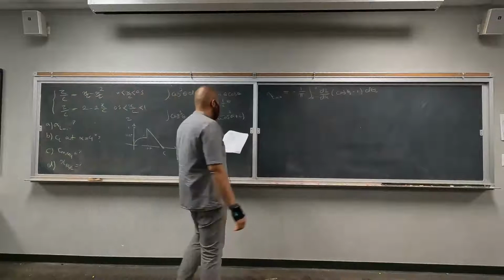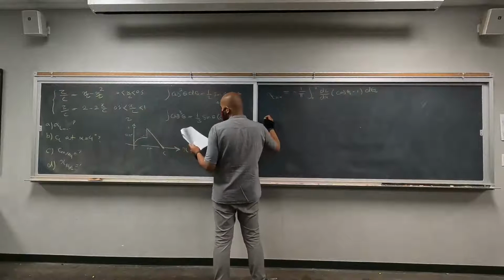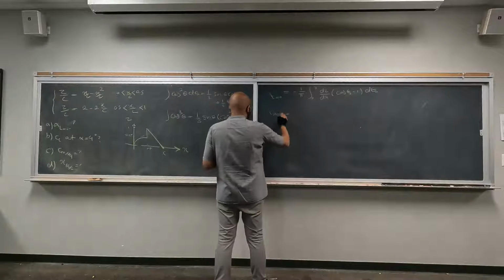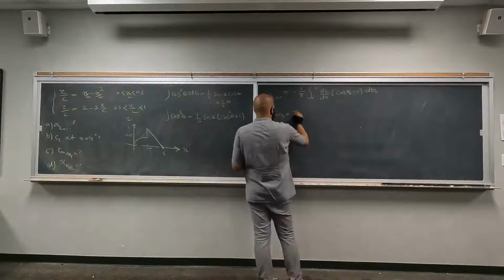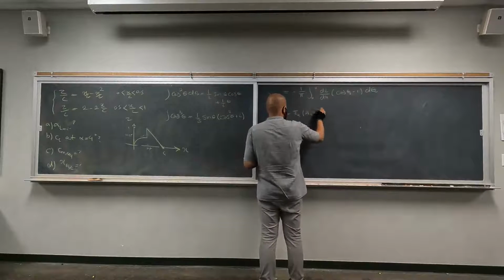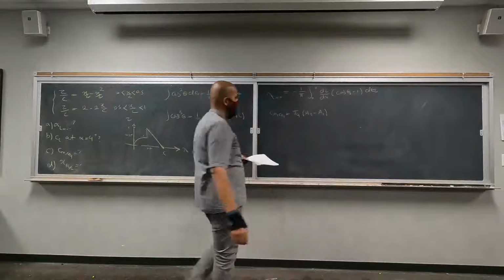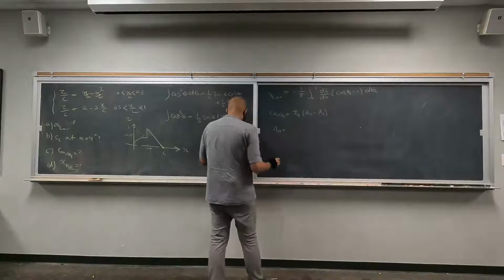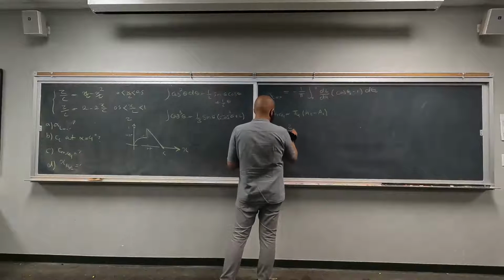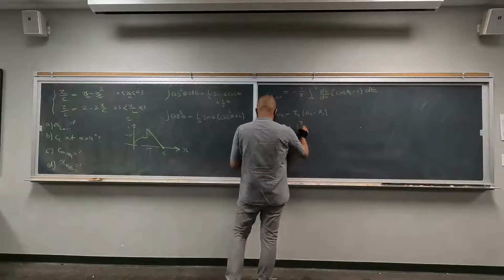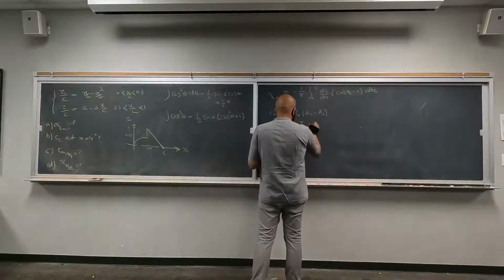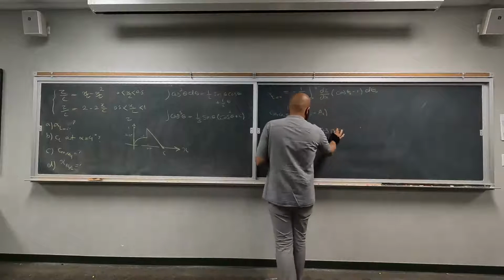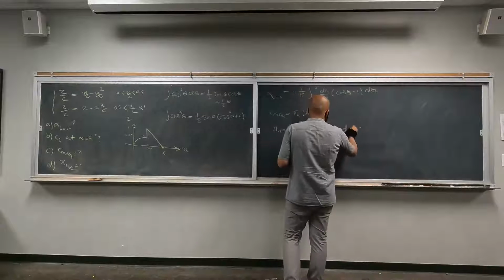And I guess for part B, you don't need an equation, but for part C, Cm around the quarter chord, you have pi over 4, A2 minus A1. A2 and A1 are your Fourier constants. A of n can be calculated as 2 over pi, integral from 0 to pi of dz/dx cosine of n theta d theta.